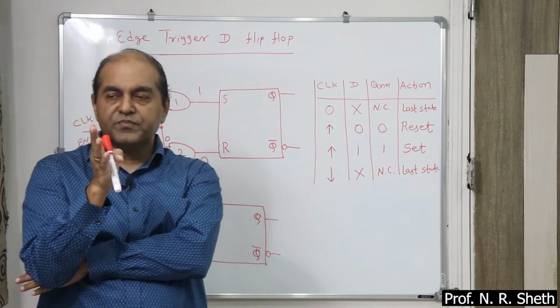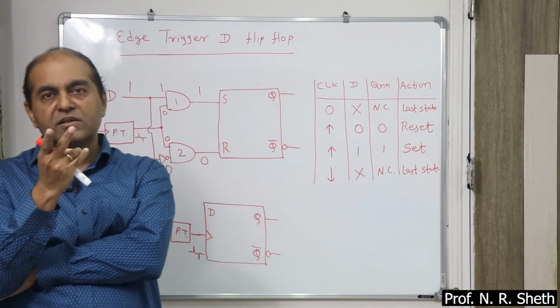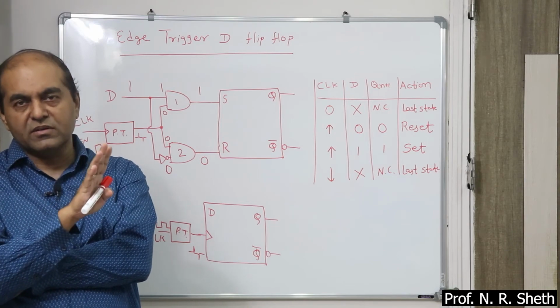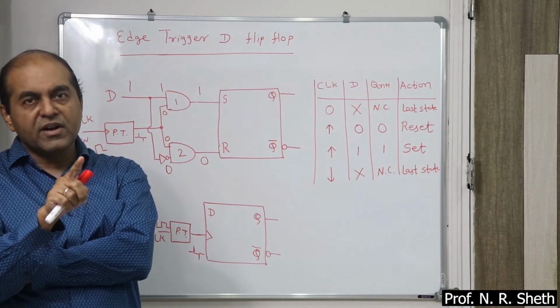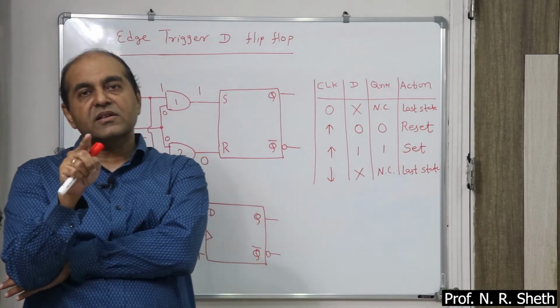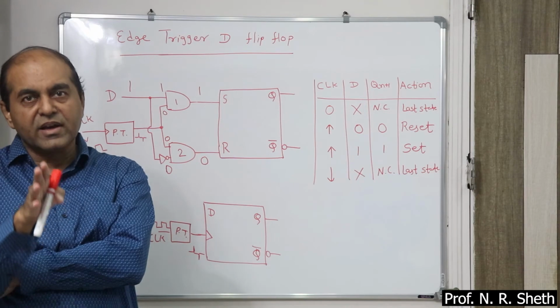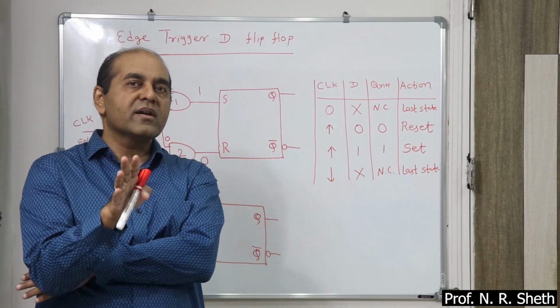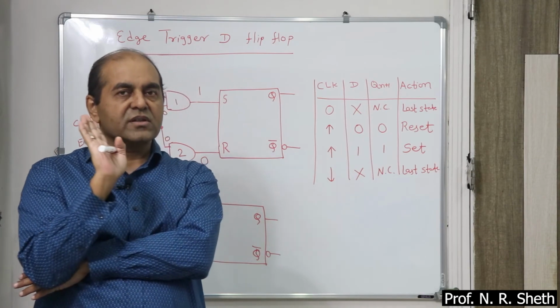Simple RS has 2 disadvantages. First, the circuit is asynchronous and second disadvantage is the forbidden state. So the first disadvantage is eliminated in clock RS. Definitely that is a synchronous circuit, but it has the problem of forbidden state, as well as one another problem added, that chances of noise signal is introduced.